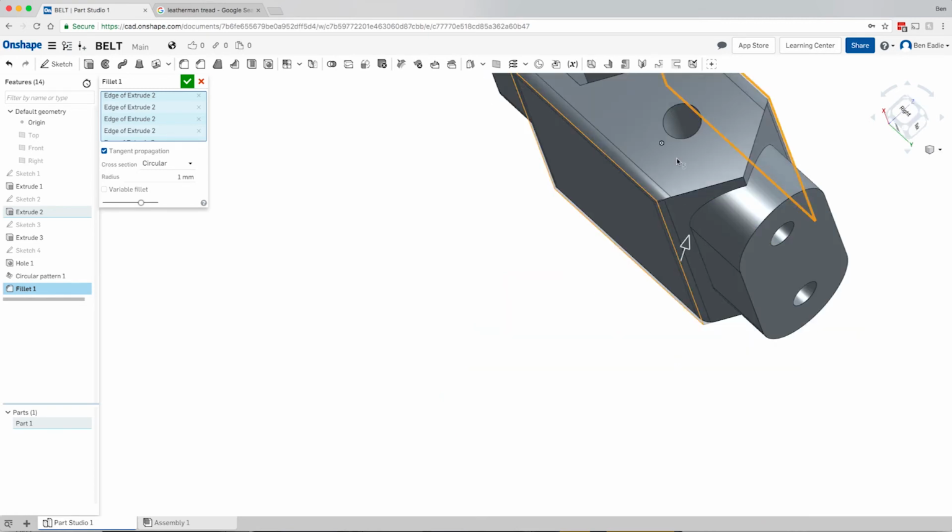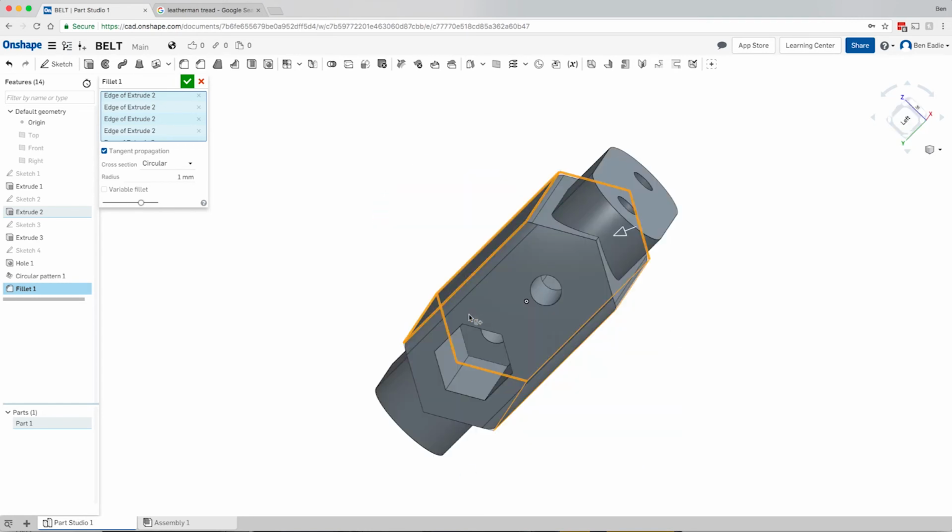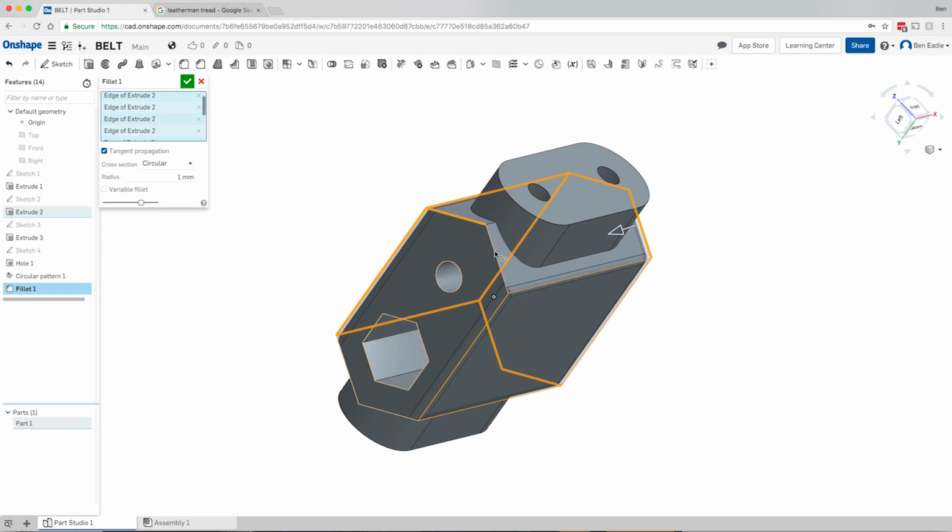In this case, I want to put chamfers on this. Chamfers work better for when you're trying to push a part into a piece, and I want a chamfer there. So if I select this face to add that fillet, it will work, but I don't want those rounded edges. There are certain circumstances where selecting edges works better, and some circumstances where selecting faces works better. So let's grab those edges, go to the other side, and grab those edges.